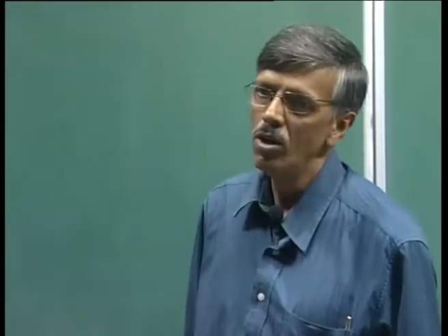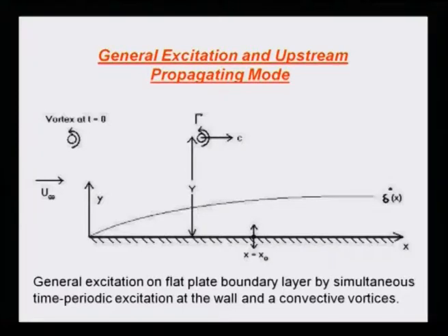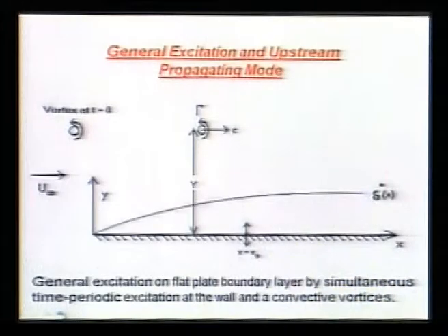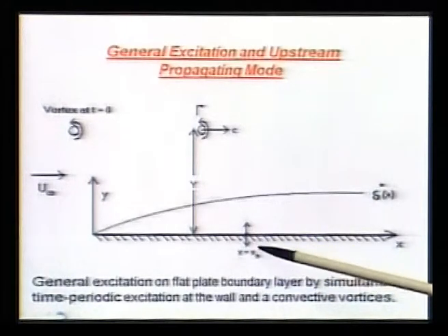So, that basically tells you that a huge area remained blank, and that area is when your fluid dynamical system is excited from outside the shear layer. Okay? And this is what happens. Let us talk about a prototypical example here, and what we need to do is consider a shear layer growing on a flat plate, and then we have a wall exciter here.